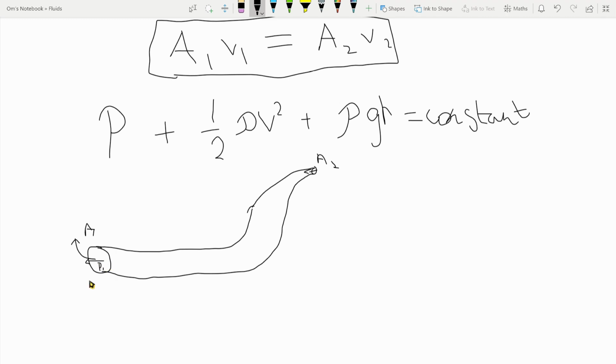Similarly, in this case, there's most likely an external force that we can consider to be, suppose, atmospheric pressure. That is also an external force here. So over here the external force is trying to push the fluid in, trying to get it to stay inside. So in this case there's actually a pressure P2 being exerted by the fluid in this direction. Similarly, you can consider the velocity, say, v1 at this point, and the velocity v2 at this point, alright?